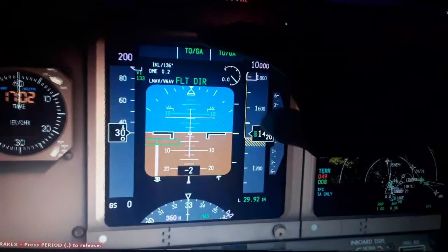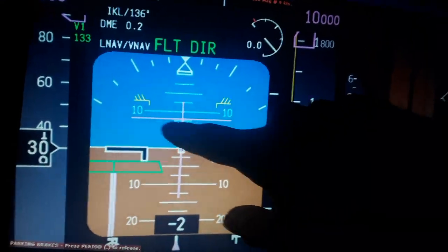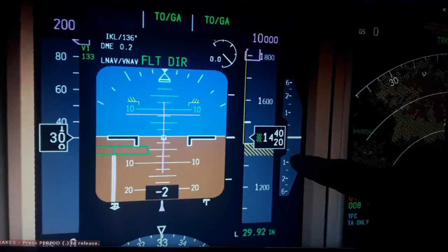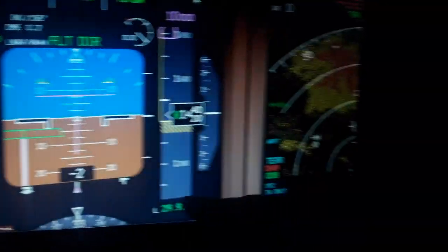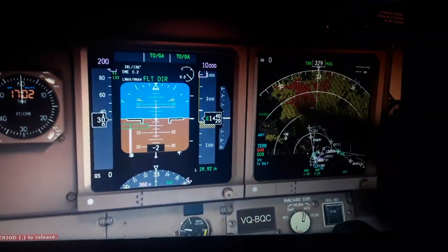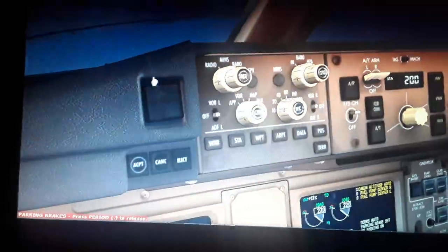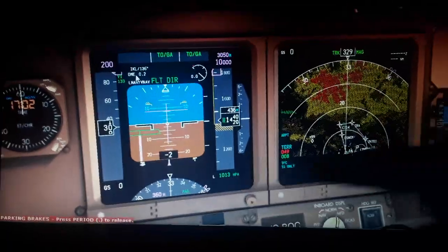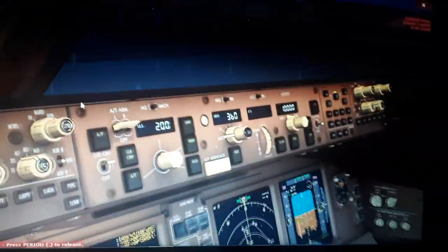The flight mode annunciator with the autopilot and auto throttle. So the aircraft might be actually pitching up, but might be actually descending, so you have to pay attention to all the instruments, like the vertical rate of climb and descent here to see if the aircraft climbs and descends. You have the magnetic heading and track. We have also the altimeter units here, the meters, hectopascals. Over here you can see, so we have the pascals, the meters. We can select other values here for the systems display.